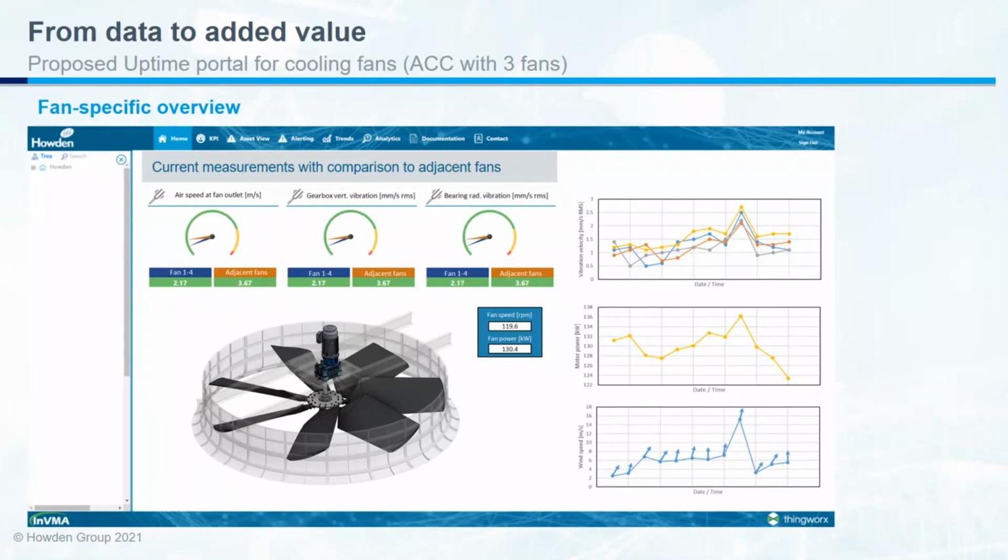We will look at vibrations over time, and what's not on this screen, we are aiming to add an FFT 3D waterfall. This is something we currently have in place for reciprocating compressors, and this will give a great view of development of your vibrations over time, but also you can see where they are developing, so it's not the total of the RMS that we are only looking at, but we are really looking at specific frequencies.